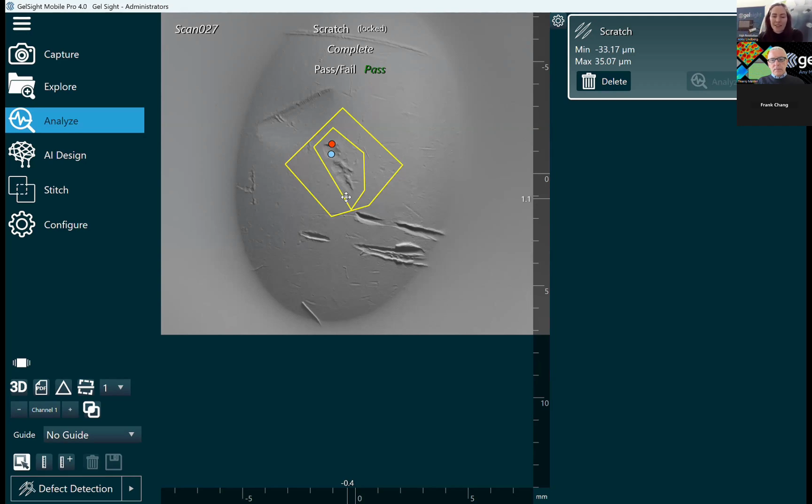If you imagine a very narrow crack that's very deep, the gel is not going to conform to the bottom of that crack. So as long as the dot peen marks are wide enough versus the depth to get to the bottom, we should have no problem with that. My experience is the dot peen marks that I've seen in the field, we get to the bottom of them. Thierry, I don't know if you wanted to add anything to that as well.